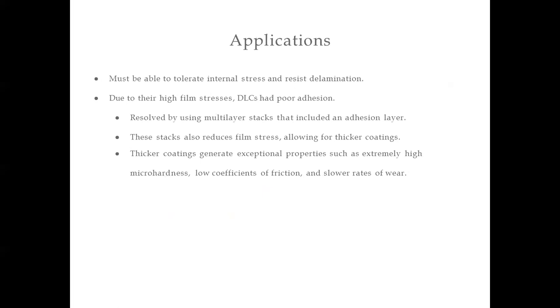This could be resolved by using multi-layer stacks that include an adhesive layer, and then layers that would be able to give some kind of mechanical movement to the DLC material. These stacks also reduce film stress, allowing thicker coatings, and thicker coatings generate exceptional properties such as extremely high microhardness, low coefficient of friction, and slower rates of wear.